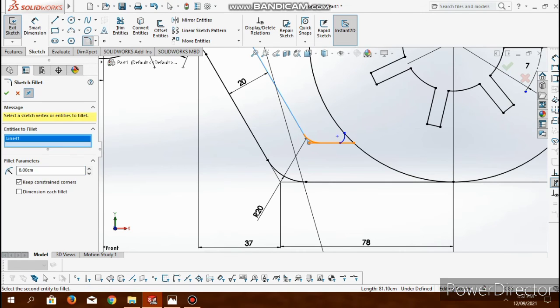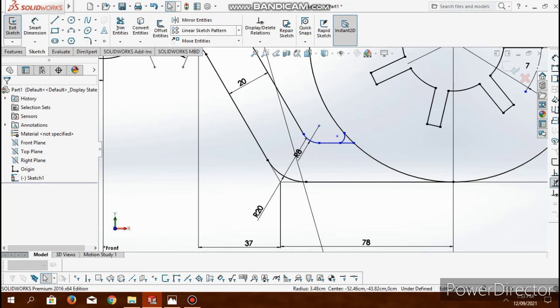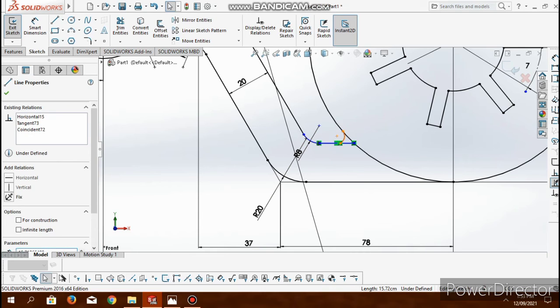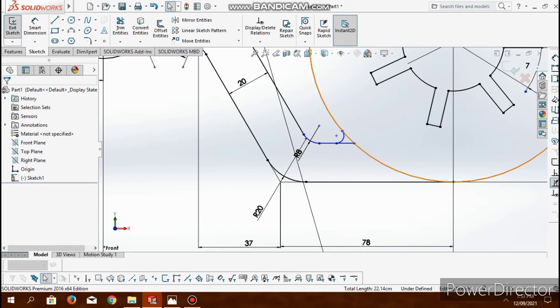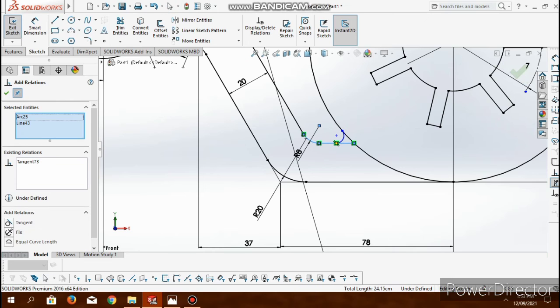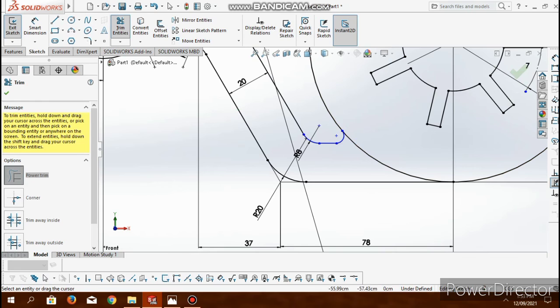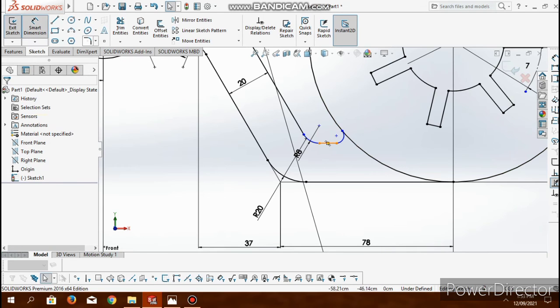Next, the diagonal line and the horizontal line will have a rounded corner, and we will use the fillet command. It must have a radius of 8. We'll now proceed with defining the new figures. Ensure that the arcs and the fillet are tangent with the other figure that it was connected with. We'll now also modify its dimension, which is 20.